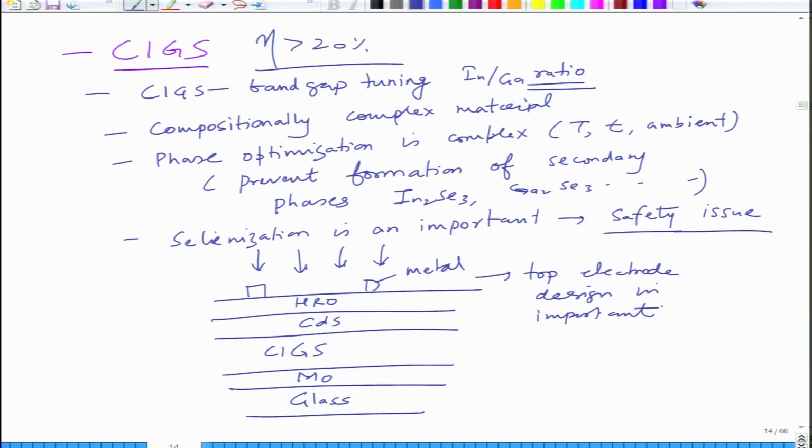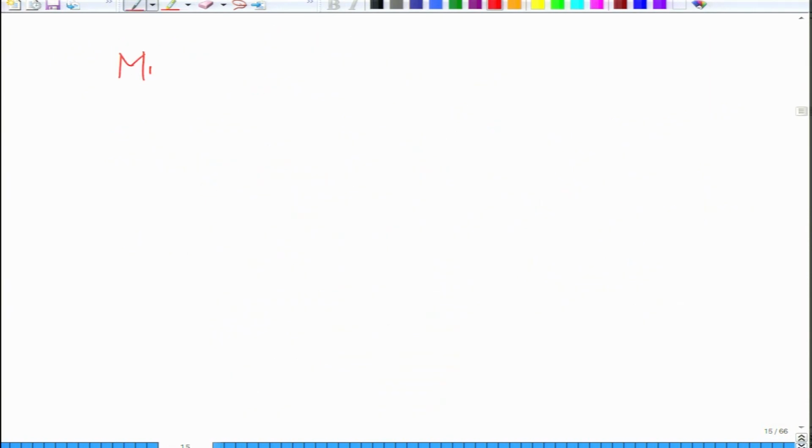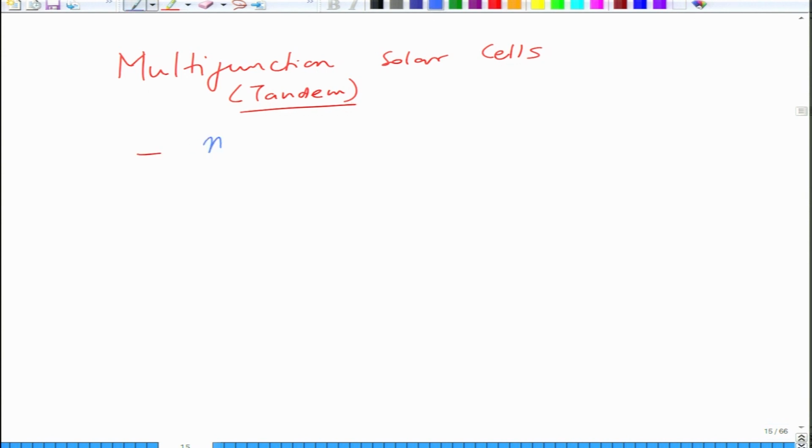And then we looked at multi-junction solar cells, which are nothing but a combination of various band gaps. You can say these are tandem cells, in which you put in multiple band gaps in tandem and increase the efficiency up to 40+%. Between 40 and 50% has been achieved by combining various materials of different band gaps. So, this is the summary of Gen 2 solar cells.